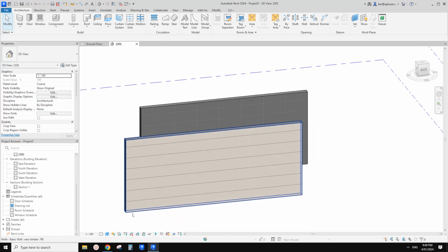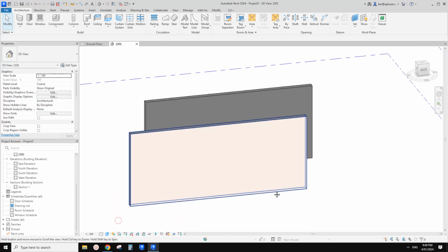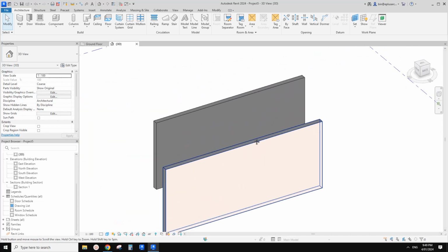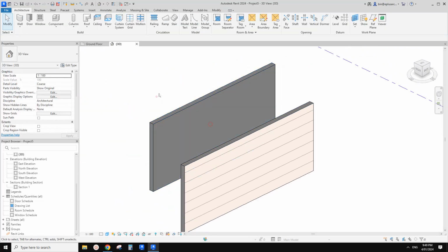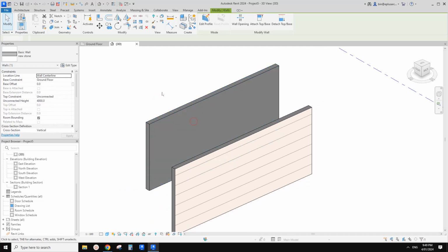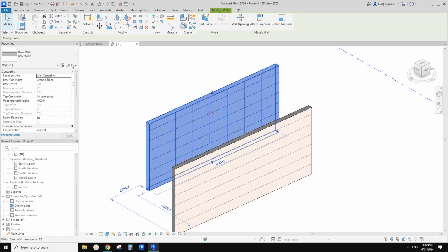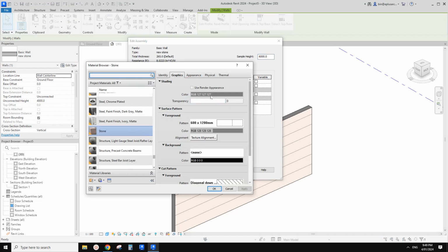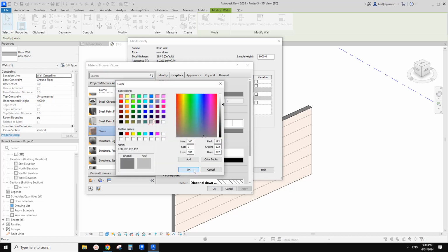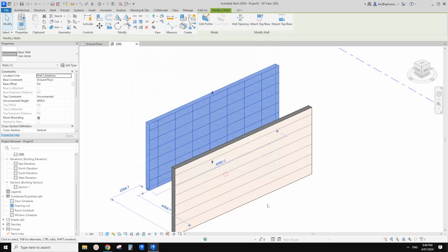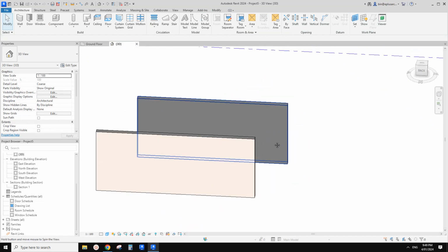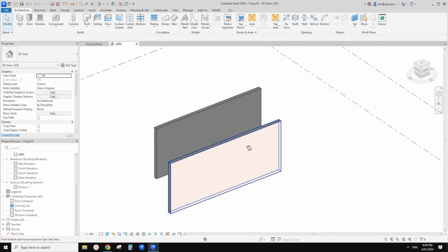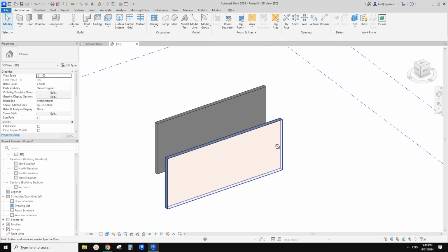Okay, and you can do the consistent color, so it will always show the same. Oh, actually, yeah, same color. So maybe it's not ideal to use that gray color for this pattern. So you can just go to edit type, click on this material, and go here. See, it's very close. This is 127, and this is 128. So maybe we should just change the color. So at least it's clearer. It's much clearer. So okay.